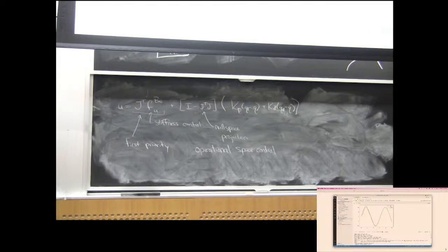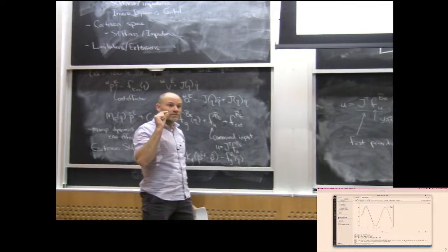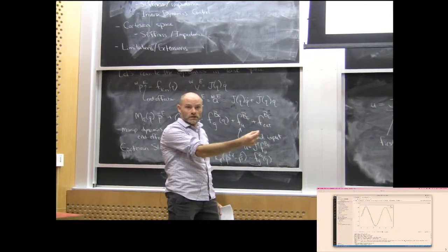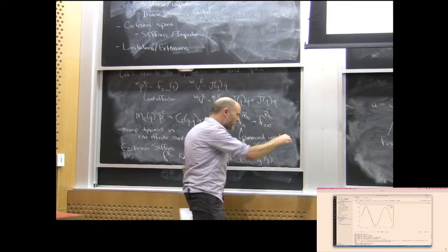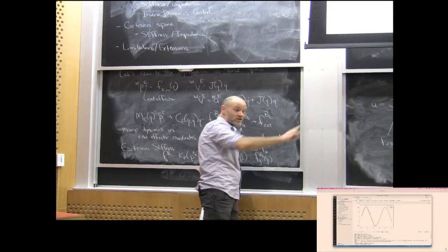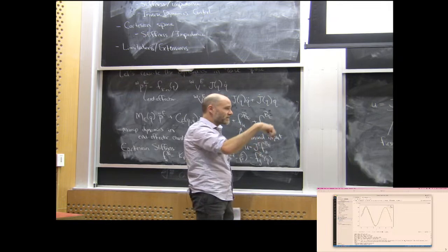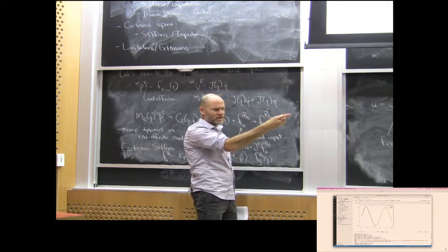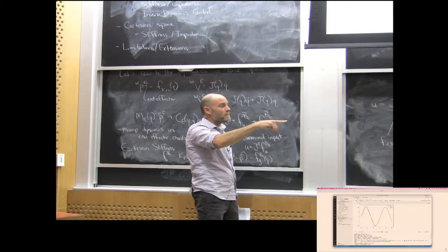All of this is based so heavily on the Jacobian, and it's the Jacobian that gets me from robot joint coordinates to a particular point on my robot. So if I'm in the factory or something and I'm applying forces exactly at the end of the orange knob on the robot, then life is good. I can act exactly like I want at the end of that orange knob. It's actually the center of that little orange sphere, I think, where the coordinate system is for us today. All right.